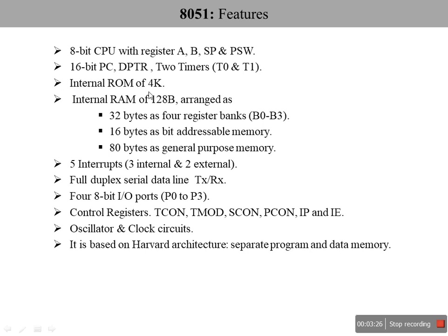The basic necessity of having this internal ROM is the same as having a hard disk for our personal computer, where we install or store the operating system and some applications. Similarly, when you want to write applications for the 8051, you have to write them, then download or burn them into the internal ROM of the 8051. The size of the internal ROM is around 4 kilobytes. That means we can write a program of 4 kilobytes that can be accommodated inside